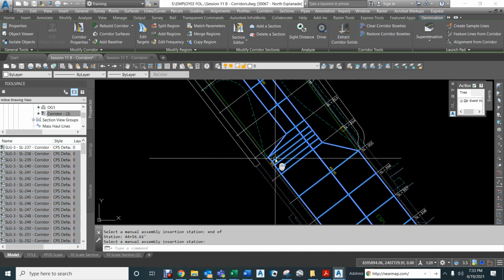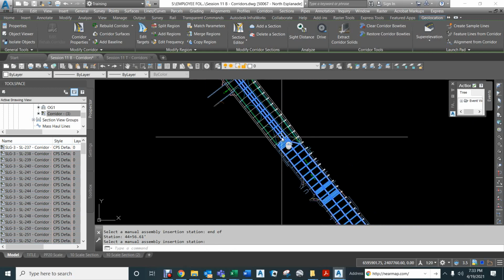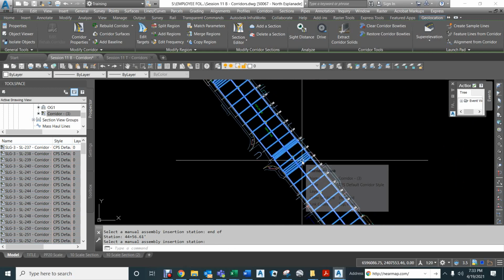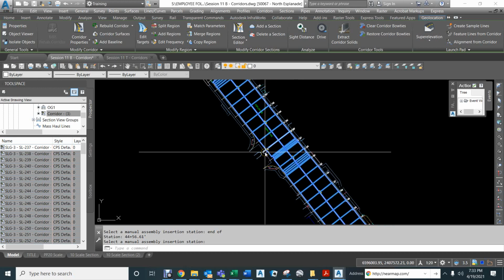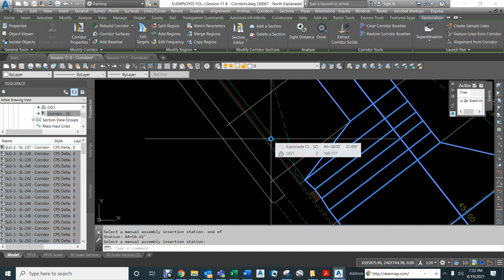And now that cross section will come out and meet there. And then again, we'll have to do some special things with this area right here. So we have targeted in the X, Y, and Z direction all of the existing lip of gutters. Now it's time to start shooting for the proposed lip of gutters.